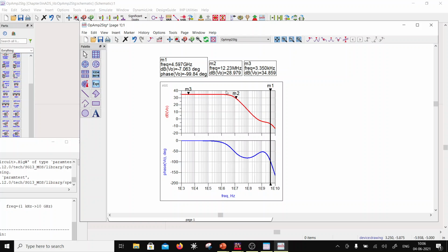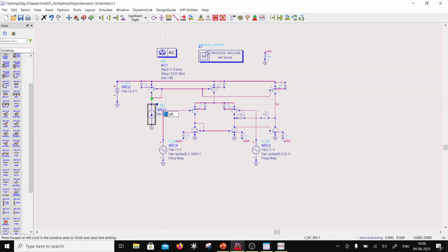Okay, so the gain hasn't gone up. The margins on the other hand have changed. I don't know why this is not working, but let's annotate DC, because if you lower the current, the output resistance goes up and the gain is supposed to go up.